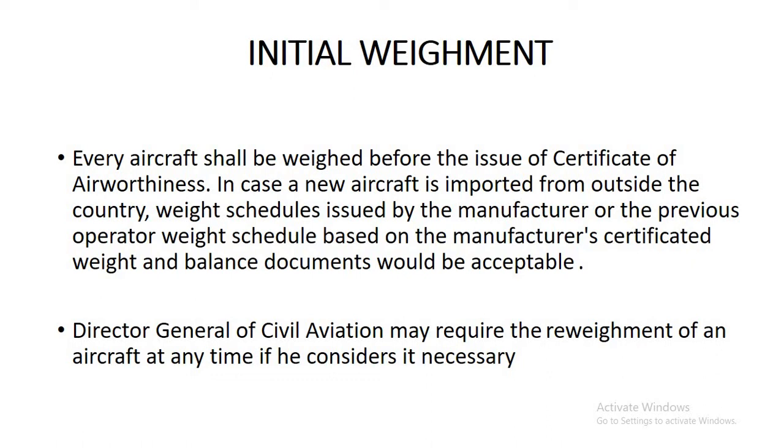In case a new aircraft is imported from outside the country, the weight schedule issued by the manufacturer, or the previous operator's weight schedule based on manufacturer certified weight and balance documents, will be acceptable to DGCA. And anytime DGCA officials can come and ask for a reweighment of the aircraft. They have the authority and power to ask for so.